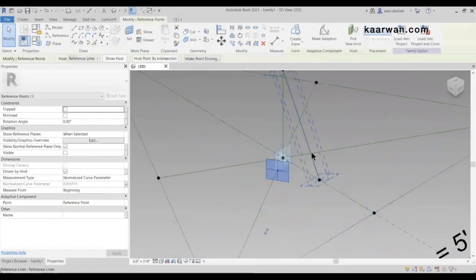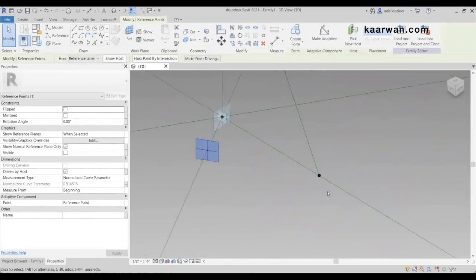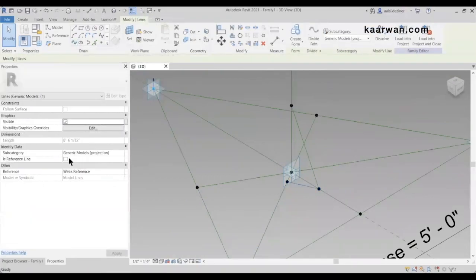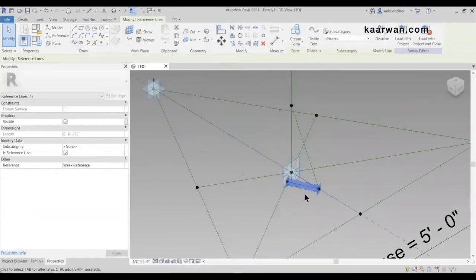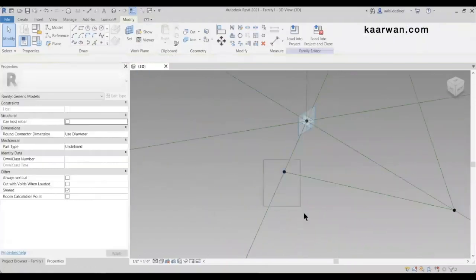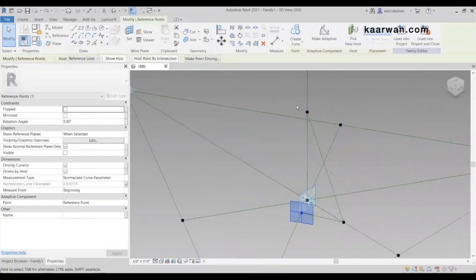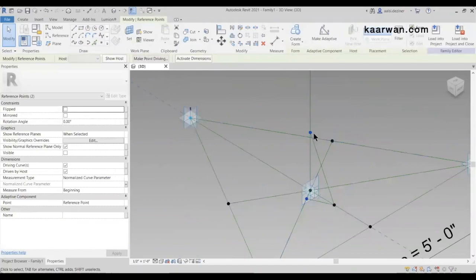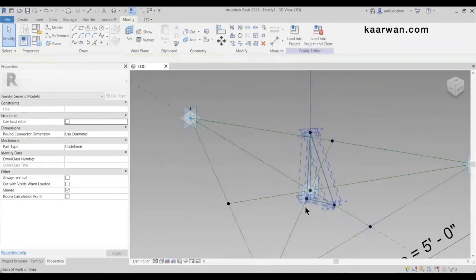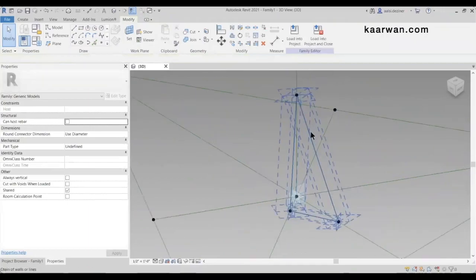Okay. Now point number 2 and the last selected point. Okay, draw a spline through these 2 points. Okay. And now join this point and the vertical point on the vertical. Spline through points. Okay. And make sure you turn this also into a reference. So make sure all these points are connected through reference lines.